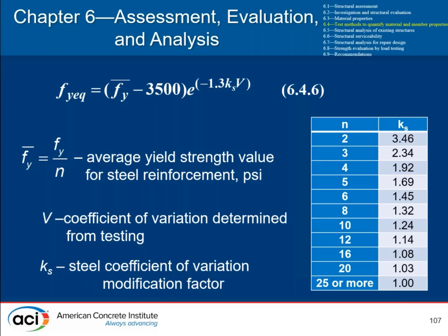The concrete strengths, especially core strengths, can be at least as variable as that assumed for new construction, but often the compressive strengths are markedly higher than the minimum specified values, especially if the concrete is old, large grain cement particles, which continue to hydrate with time.